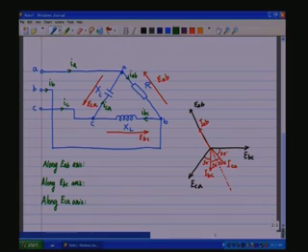So, if we take along the EAB axis, you will see that along this axis there is an IAB term, then there would be a projection of ICA onto this axis, and a projection of IBC onto this axis. All these 3 together form the equivalent current along this axis.